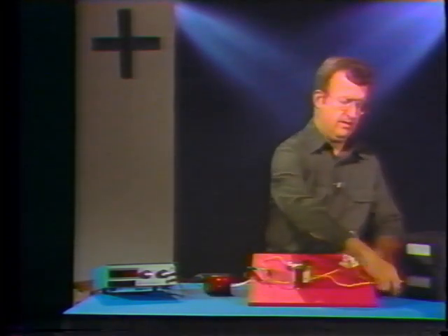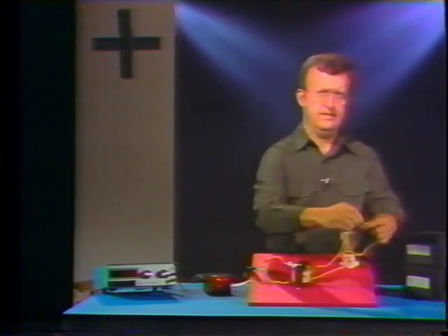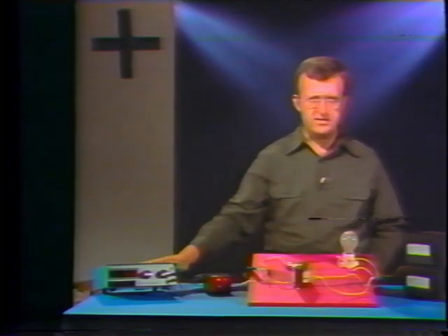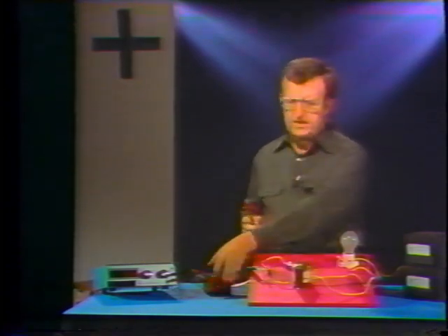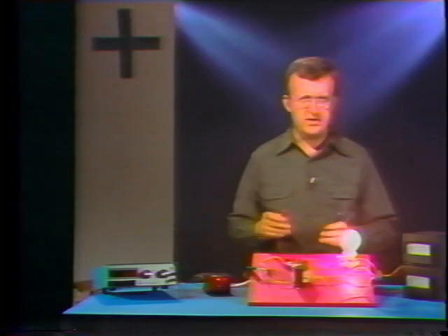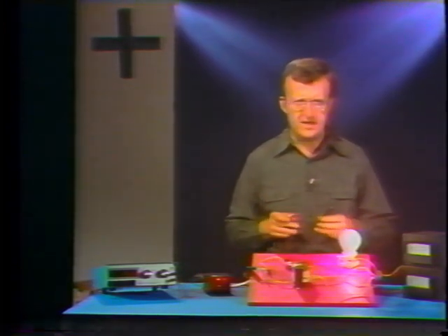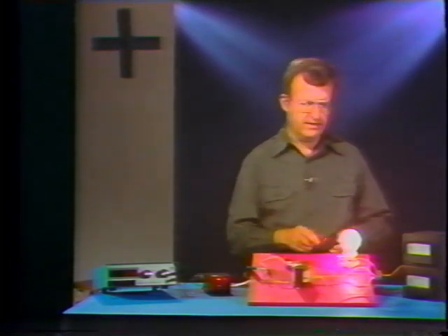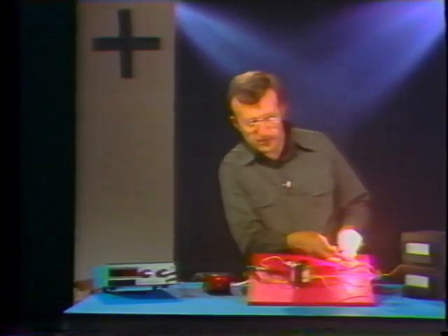Okay, now we're going to disconnect things here, and let's see what effect this transformer has on voltage and current. I can use a voltmeter to check the input voltage and the output voltage. The input voltage, the primary, should be 120 volts, and it is. We figured that the output voltage, the secondary, should be 12 volts because the primary winding has 10 times as many turns as the secondary winding, so I'll use the voltmeter to check the secondary. Right again, the output voltage is just about 12 volts.